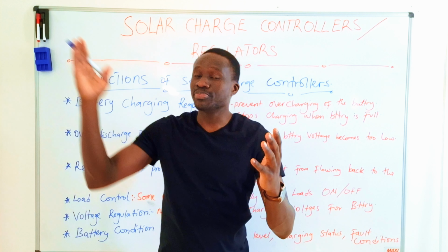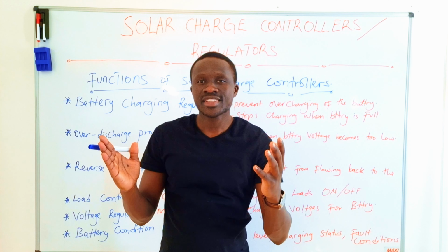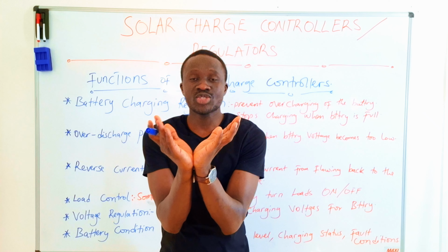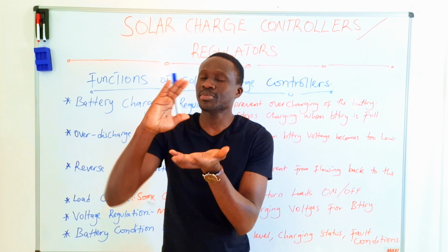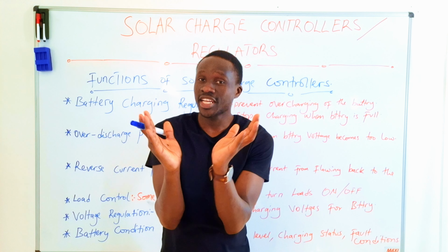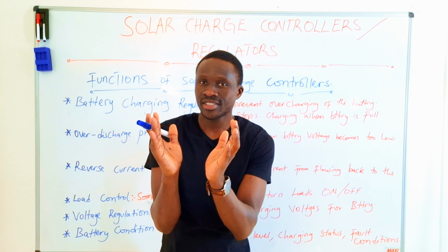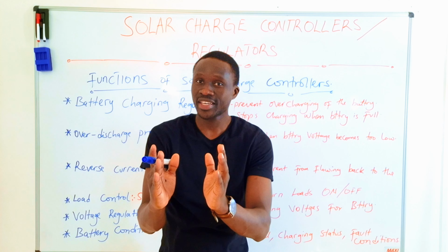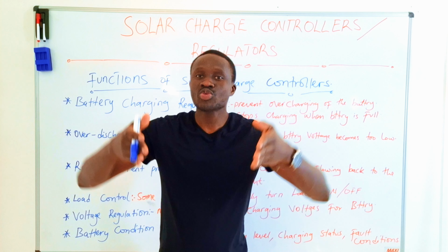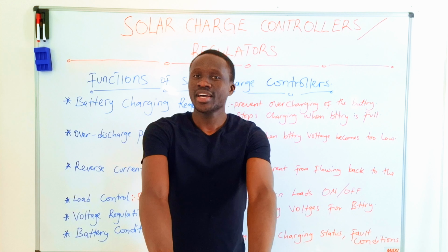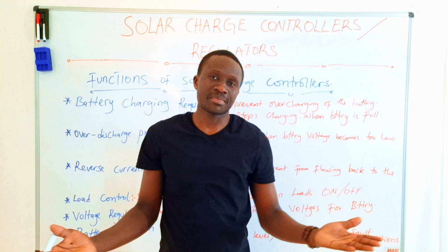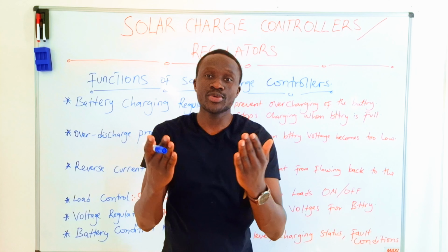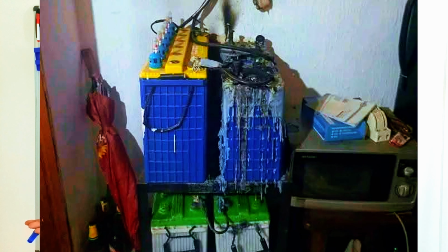Yet our solar panel is bringing 21 volts. Okay, now this regulator will regulate this 21 volts. It controls the voltage. It brings only 15 volts for the battery to charge. Without the regulator, 21 volts will go direct to the battery, and our battery, with time, very soon you will again get a call, or a customer will call you that the battery is dead,